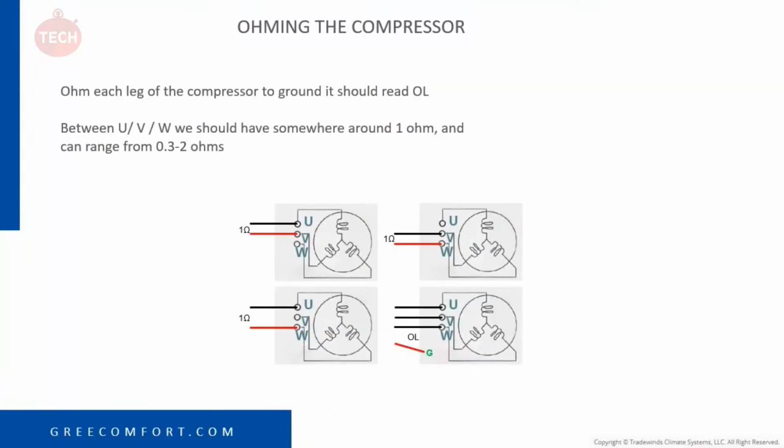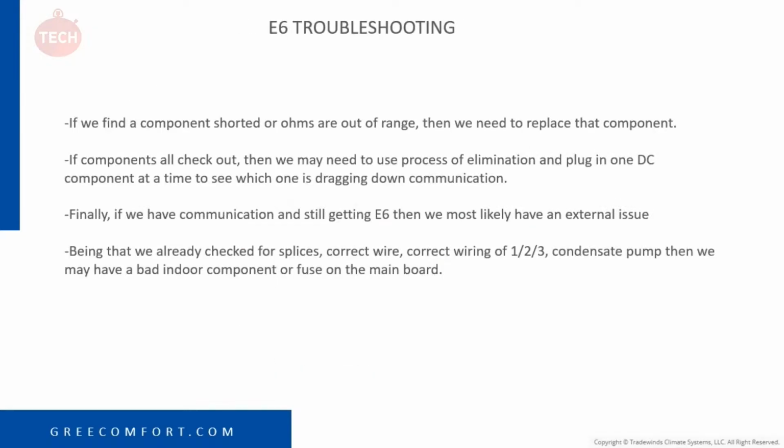Again, you can always check your meter, touch your meter leads together, make sure that we're reading 0.0. That way we know your meter leads are good and your battery is good, before we even do these readings. So, get into a little more here.